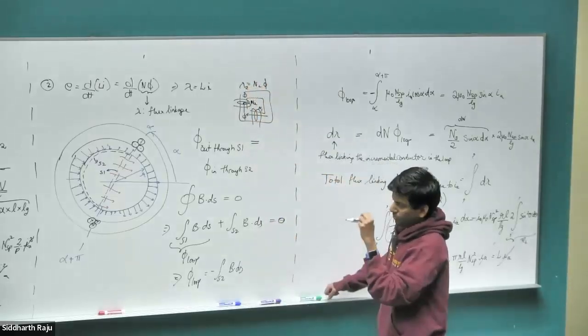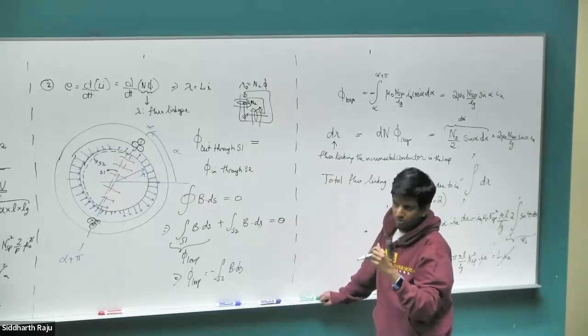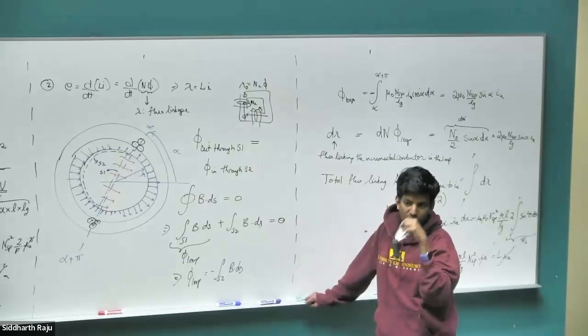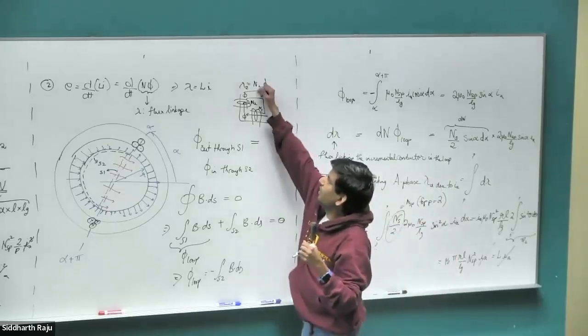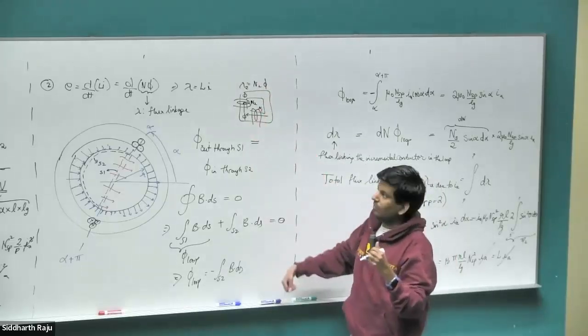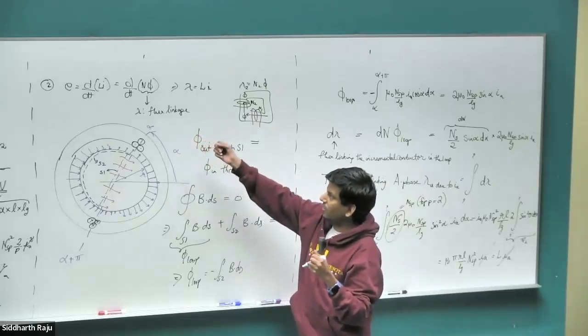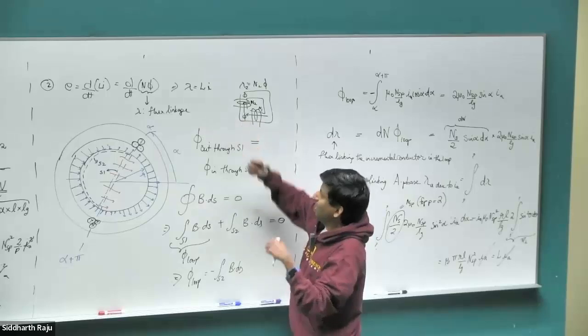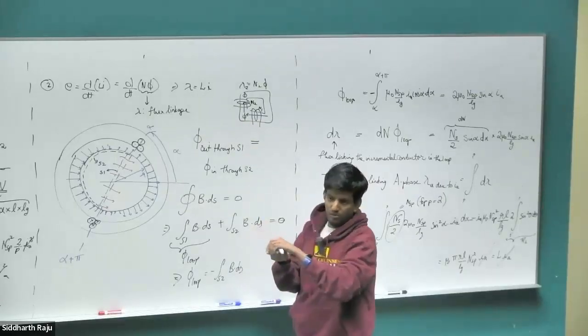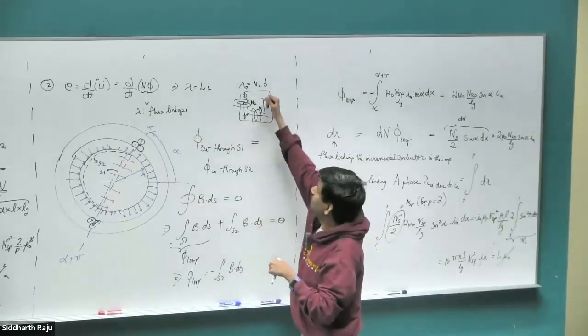That's it. Because each of those coils, when flux changes across it, is going to create an EMF. And if there are N coils, those EMFs add up. Right? That is what we are capturing by multiplying N2 times φ. So that when we do the dλ/dt, that will give us our EMF, and that λ captures the fact that N number of coils are linking to the single flux φ. Right? So that's what we are doing by this multiplication there.